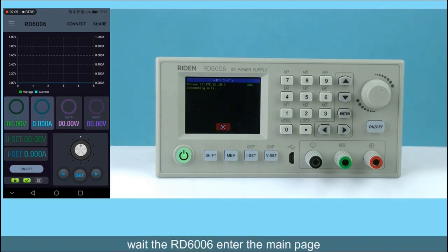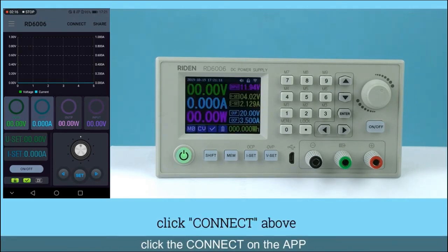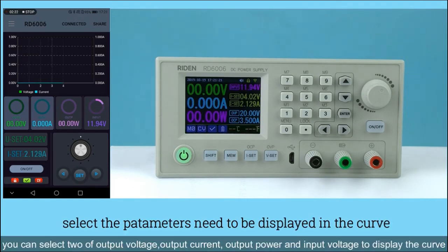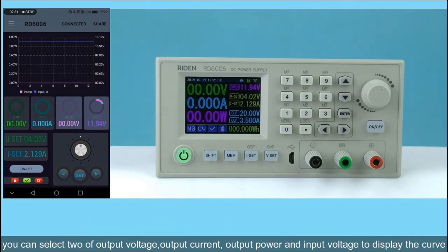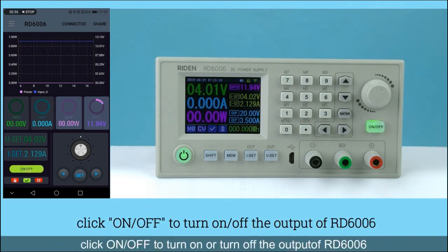With the RD6006, enter the main page. Click Connect above. You can select two of output voltage, output current, output power, and input voltage to display the curve. Click On/Off to turn on or turn off the output of RD6006.